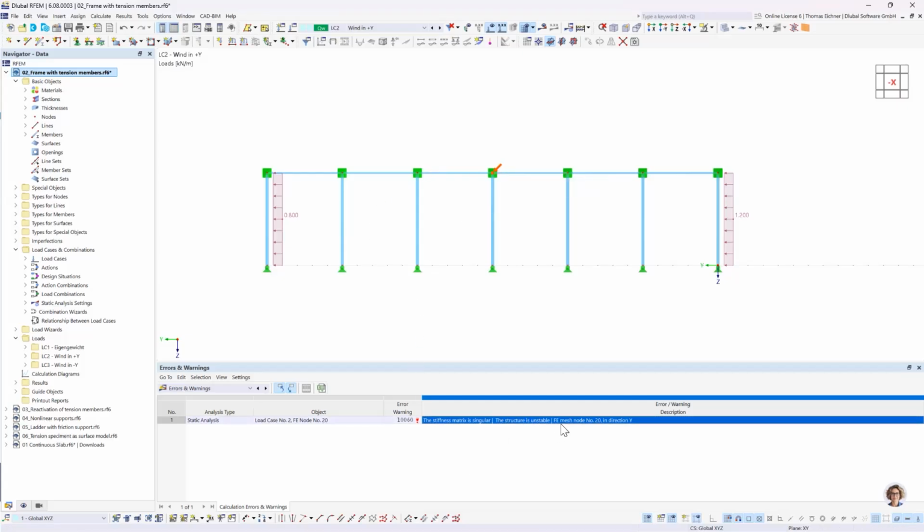And it also gives us a hinge at this node in y direction. Y is here. So it would just fall down in this direction, right? All these members would rotate around their supports, and this would just go boom. Well, that's a problem, so we want to do something against it.